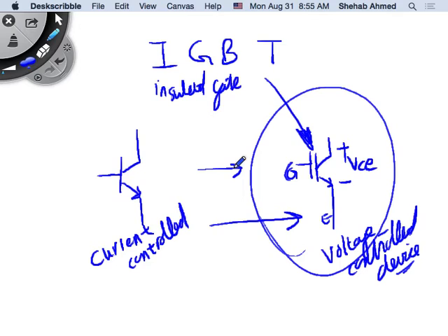They're faster. They can turn on and turn off faster, which means that they have some advantage in very low power applications, small, tiny applications. In very, very high voltages and very high currents, SCRs and thyristors are really the big workhorse. But then everywhere in between, the IGBT is the master, right? So open a motor drive for a fan, open a motor drive for an air conditioner, open a motor drive for whatever application, open a UPS, open I don't know, any power electronic device otherwise, you will find the IGBT. Okay, so that is the workhorse of the power electronics industry.